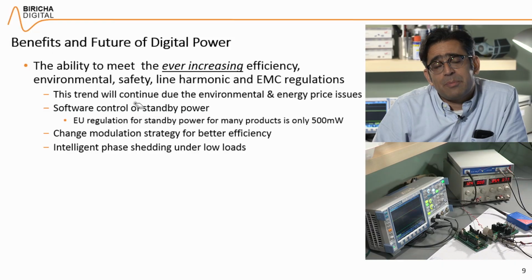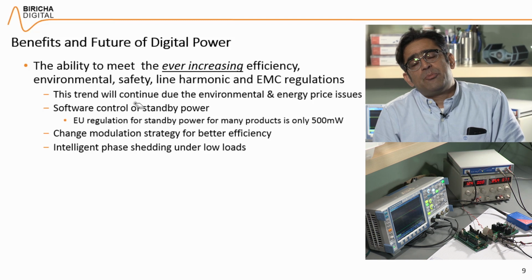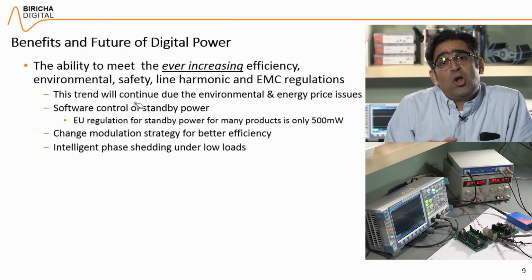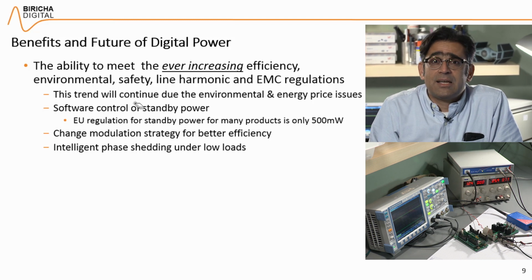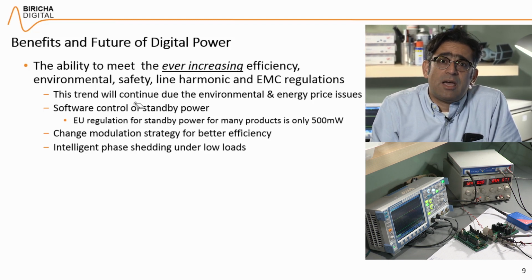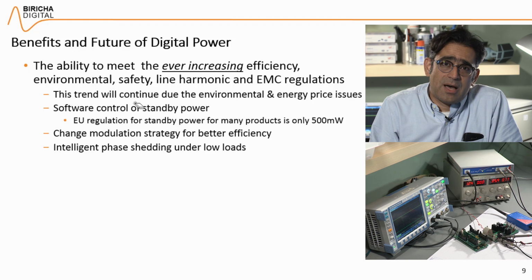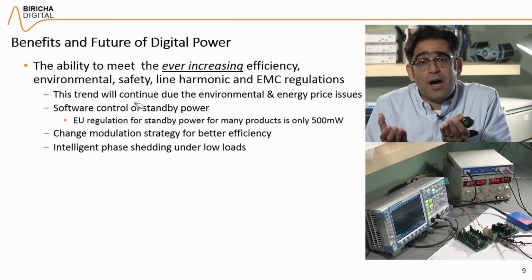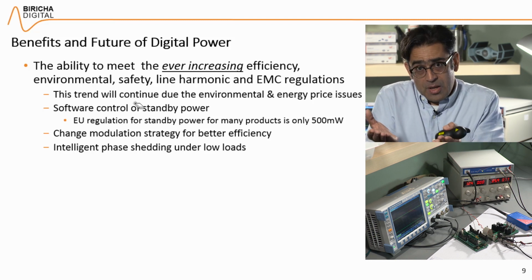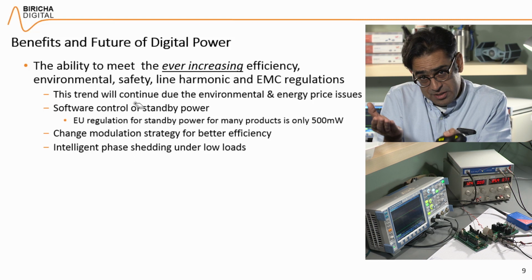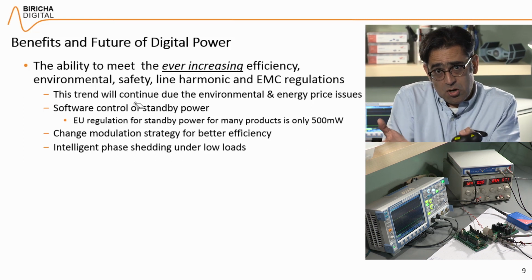Again, this is one of those efficiency requirements. Power supplies typically perform very poorly at low loads in terms of efficiency. So instead of, let's say, designing a 1 kilowatt power supply, you can design 2 500 watt power supplies and turn them on as the load goes up each stage and turn them off as the load goes down.